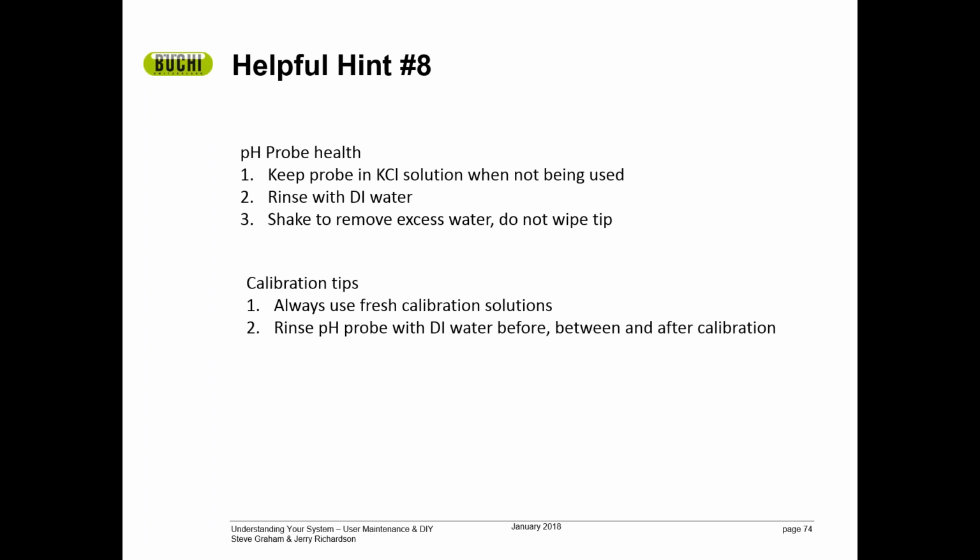Always, when you're doing calibration, always use fresh calibration solutions. Rinse the pH probe between each calibration solution and shake the water off of it.